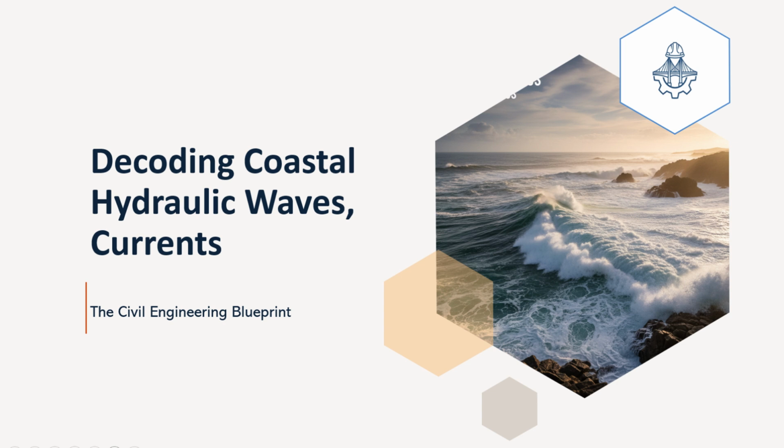You can often see this on the ocean. Individual waves appear to form at the back of a group, travel through the group faster than the group itself, and then disappear at the front. The group as a whole moves slower. In shallow water, d/L less than 1/25, n approaches 1. Here the group and phase velocities become nearly identical. The wave shape and the energy travel together.